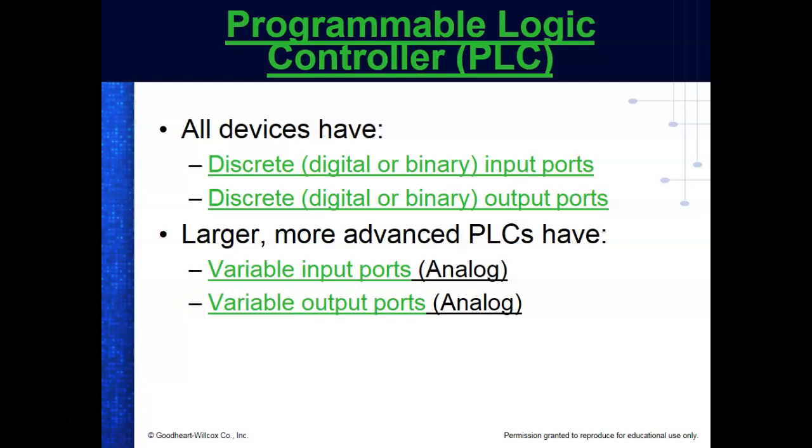True or false. But a lot of times, especially computers or programmable controllers, have to deal with what we call analog signals. Analog signals are something that varies all over the place between set limits. So analog would be like temperature, a lot of lighting and stuff like that. Speed might be analog, right? You understand that? So some of your PLCs have analog ports on them. Some of them are on there by default. Some of them you have to order and put them on there yourself, right? Does that make sense? So analog signals and digital signals, do you all understand the difference?